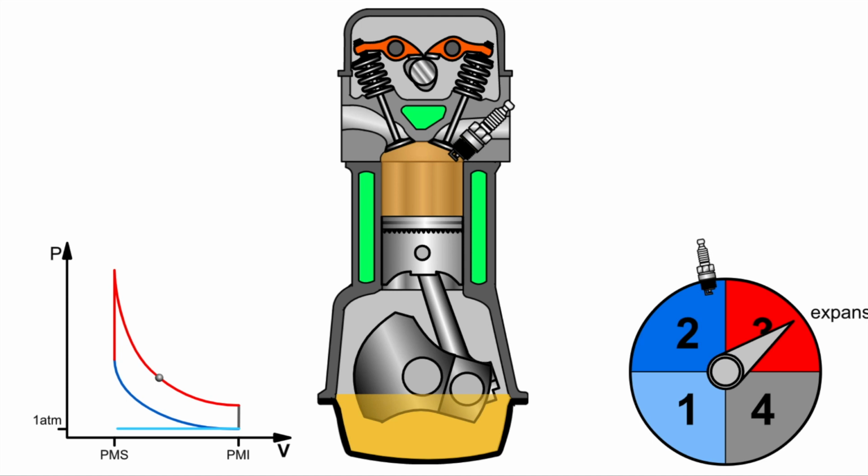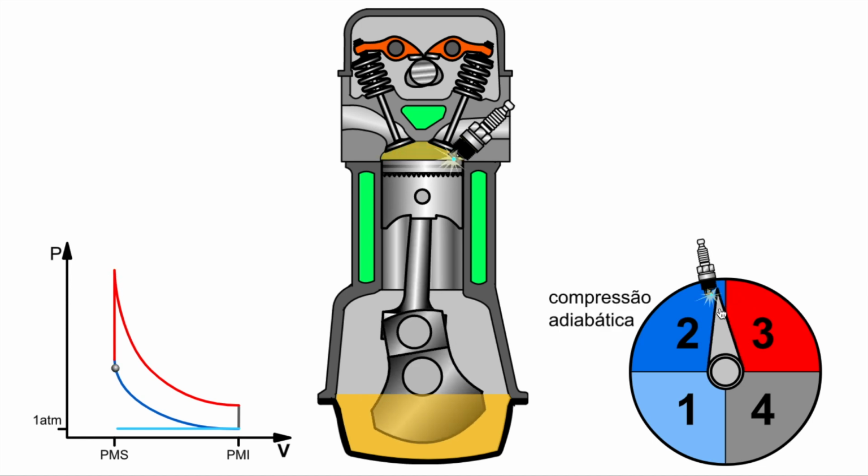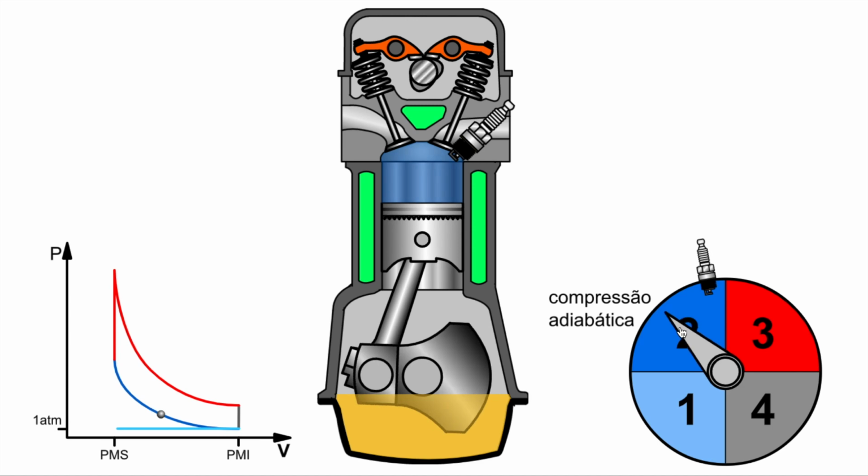So the challenge with ignition timing is to design a system that can fire the spark late in order to start the car, but then as the car runs and speeds up, to fire it earlier and earlier to convert the maximum amount of combustion energy into power, but never firing it too early. Because even when the piston's moving fast, if you trigger the combustion too soon, you'll send a shock wave down through the piston, into the connecting rod, into the crankshaft, and you can damage the engine pretty seriously. That is called knock, and we'll get to knock in another video.